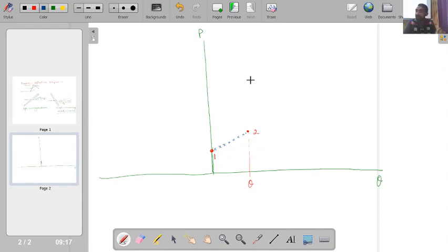So from where am I taking this conclusion? If you see our theta-beta-M diagram, how it looks, something like this. Corresponding to this situation, we have a very weak wave, which will not change the pressure, like a Mach wave. So you can see this exit and entry point will be the same.